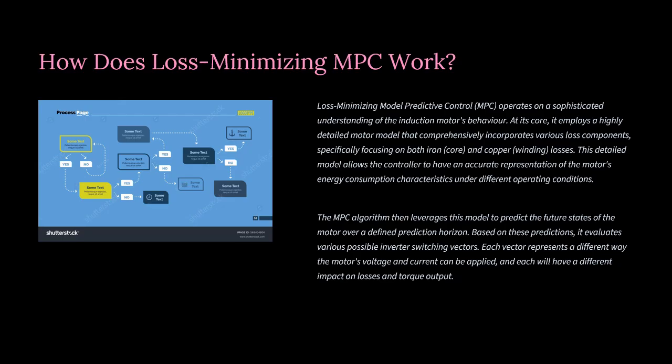How does loss minimizing MPC work? MPC means model predictive control. It operates through an understanding of induction motor behavior. The core employs highly detailed motor modeling, comprehensively incorporating various losses and components, specifically focusing on both iron core and copper losses, winding losses.